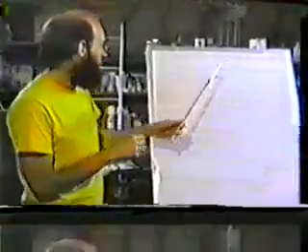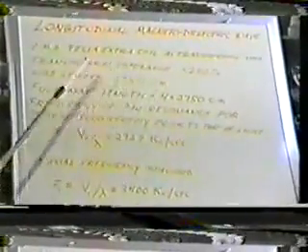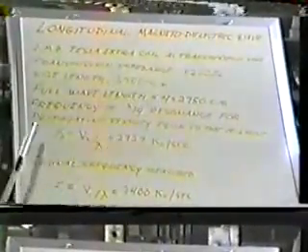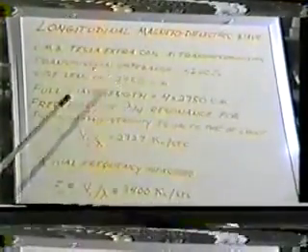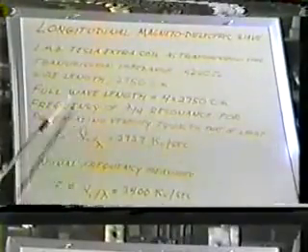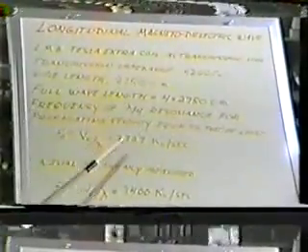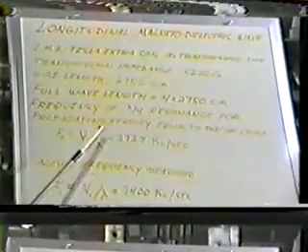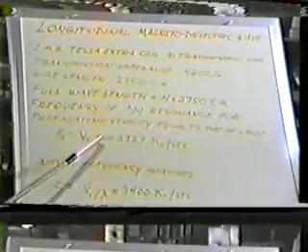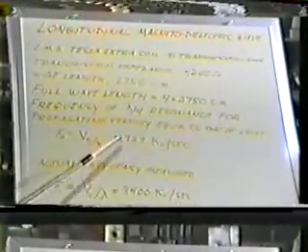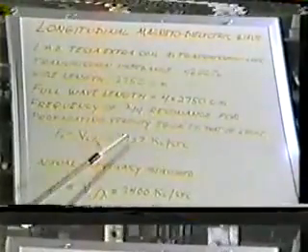Okay, covering the test data here for a longitudinal magnetodielectric wave, our LMD wave structure was a Tesla extra coil. Transmission impedance of this was 4,200 ohms. Wire length, again, is 2750 centimeters to make it analogous to our roll of coaxial cable. And again, the full wavelength would be 11,000 centimeters, 4 times 2750. So the frequency of quarter wave resonance for a propagating velocity of this length equaling that of light would be 27 kilocycles, such as before.